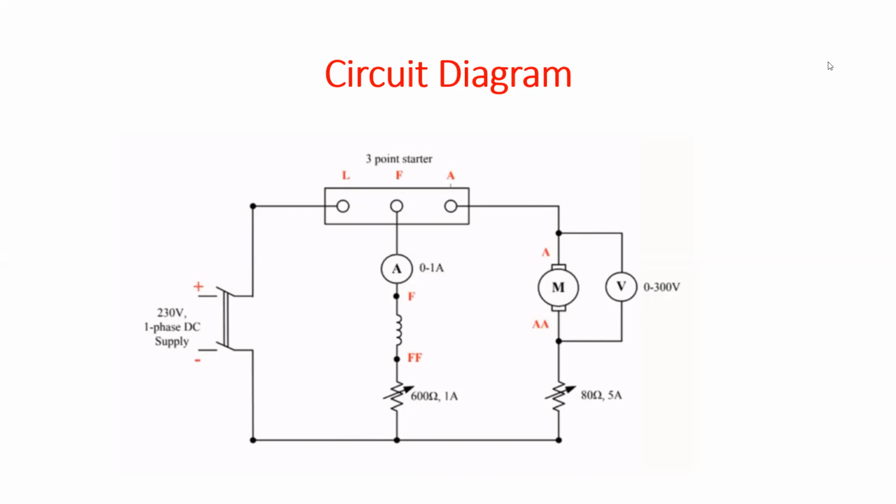A very simple circuit is there in which a relay is used, and the coil of the relay is placed in the field circuit, so that whenever field current flows through the coil, it is magnetized and energized. The NC and NO contacts of the relay are connected in the armature circuitry.